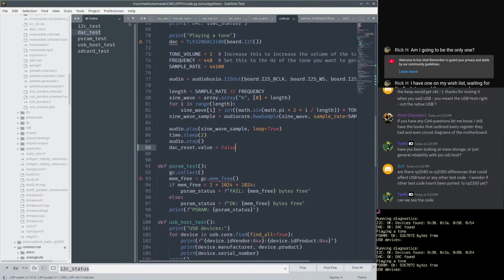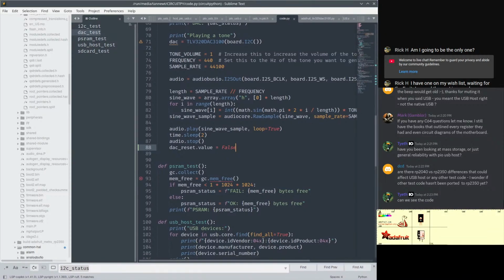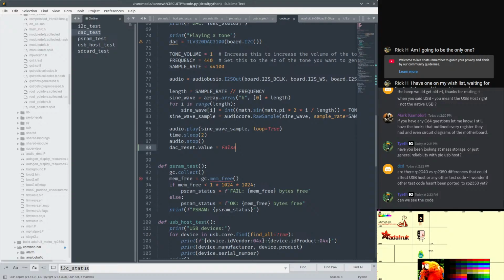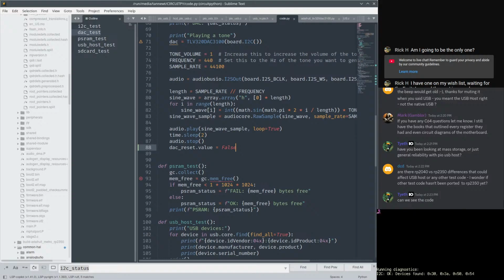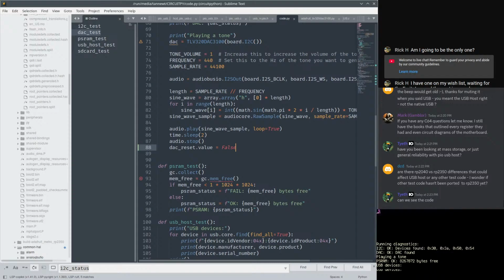And because the CPUs run at different speeds, that's something that could bother it. Also on the RP2350, I'm running the HSTX stuff, so my DMA bus is pretty busy. There's also this E9 errata that has to do with pull downs and the GPIO itself. I was wondering whether that had some impact on it too.